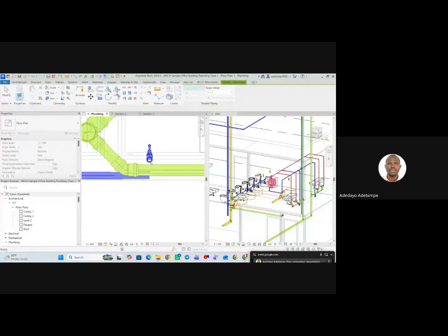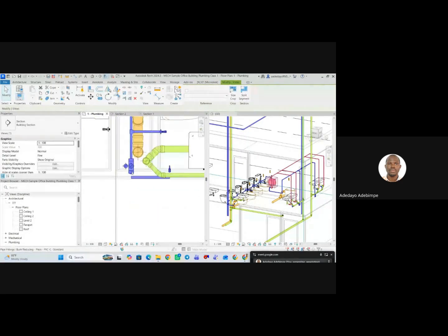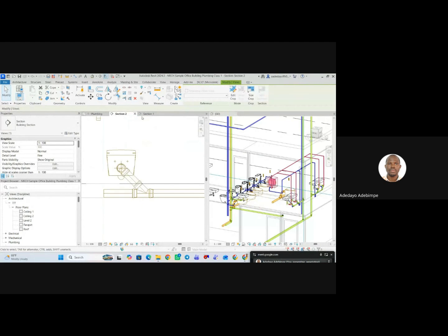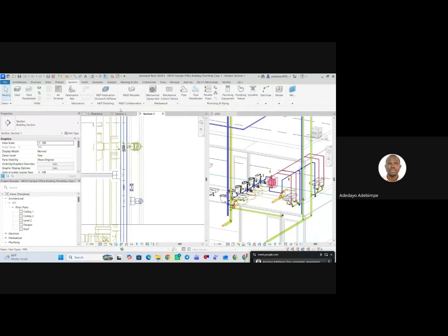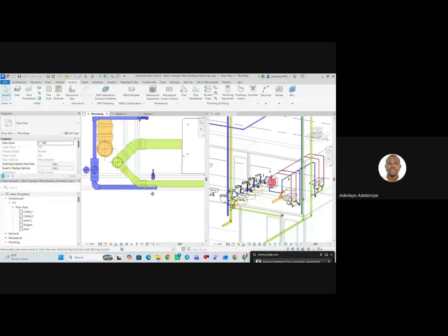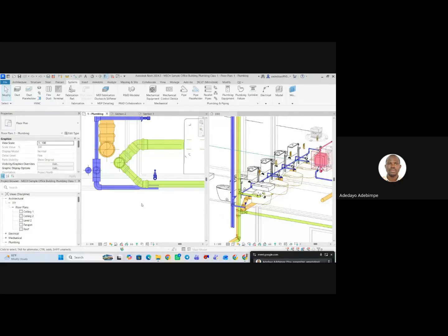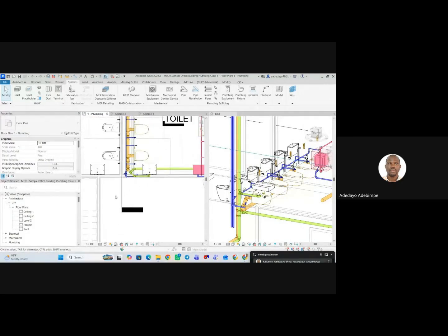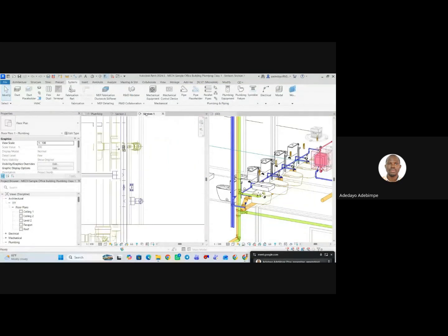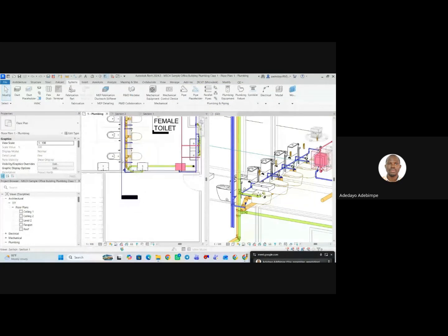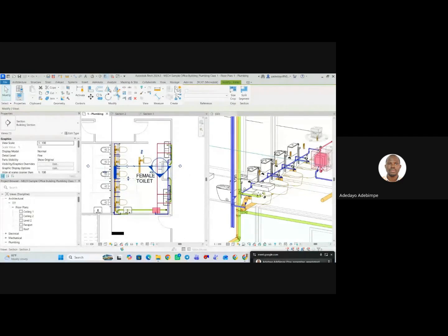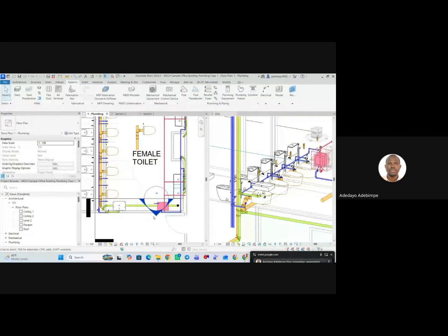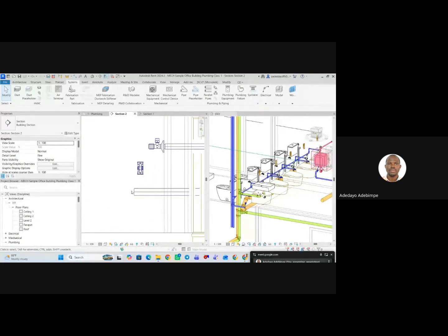So it's saying not enough space. So you see that when designing in Revit, you will probably need to toggle between a lot of views. Control Z. You probably need to toggle between a lot of views to achieve our aim. So I'll go to a section again. Let me look for a smaller section. RO to rotate 90 degrees. Then go here. So I want to see what is happening.